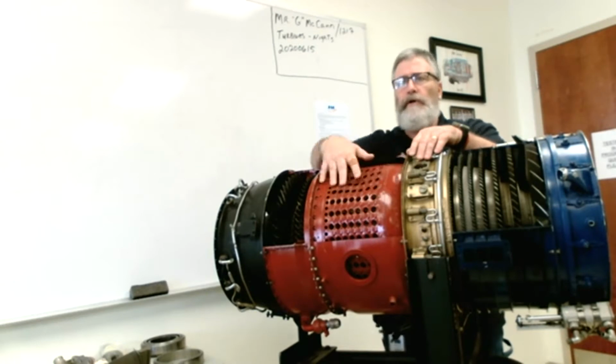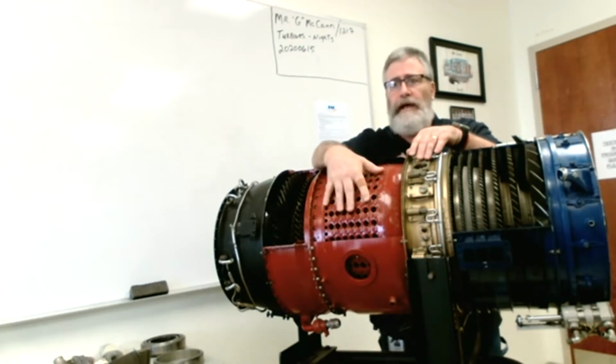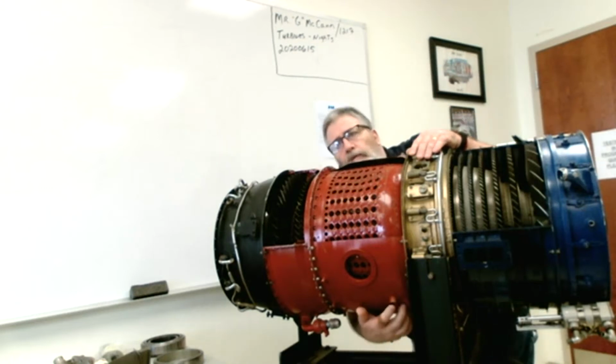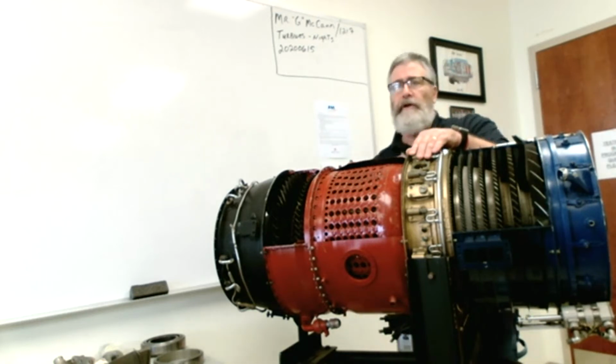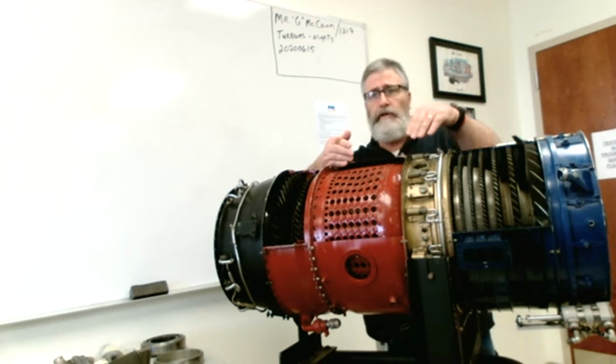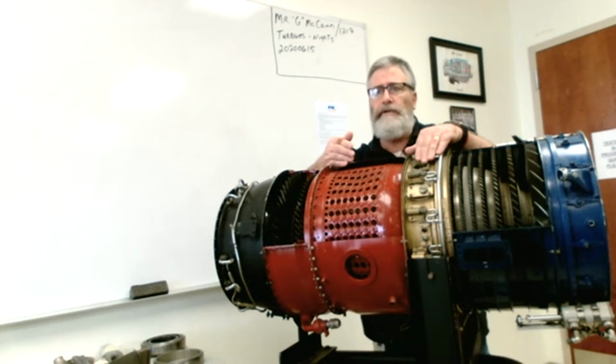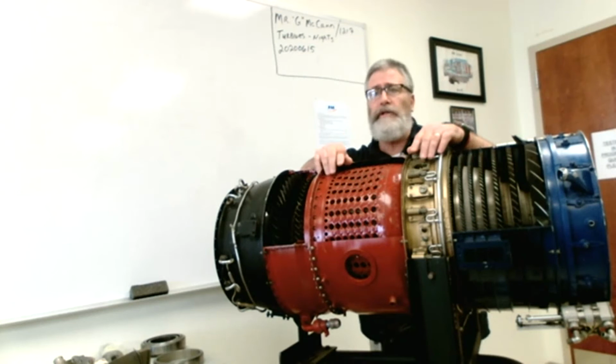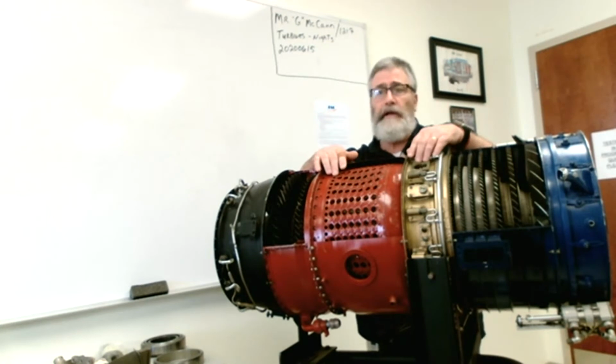Okay, something else that all combustion chambers must have. They must have a source of ignition, right? Now this has been removed, but there would be an igniter here. Different engines use a different number of igniters, just like they use a different number of fuel nozzles. But when you get to your FAA question, they're going to ask how many igniters are common on a turbine